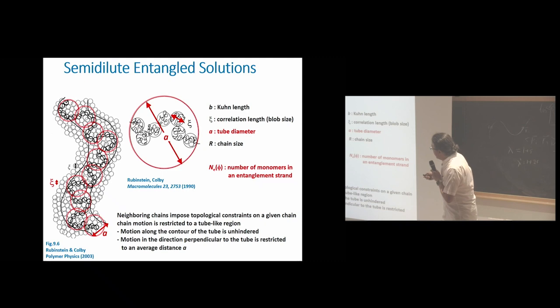Okay, so in a given chain emphasized here, it is confined in a tube by entanglement with other chains, so its size is roughly a. So the chain can move in this distance, but not beyond. Okay, there can be multiple chains. And in this tube, there is not only one chain, in fact. There are other chains. The blob is space filling, in fact, so between blobs it repels, but other chains can be inside. So the number of chain strands is about 20. Okay?